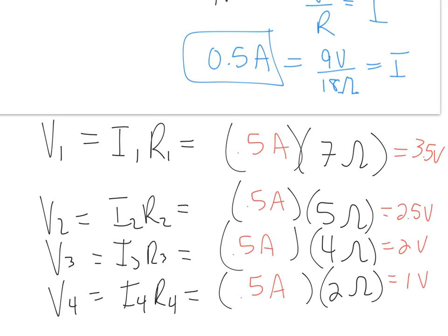So it looks like when we actually connect this to the switch, there's probably internal resistance in the switch. So the switch is actually probably carrying some of that voltage. Because this was 1.5 volts, yet we got 0.7, 0.6, which only adds up to 1.3. So there's loss of voltage.